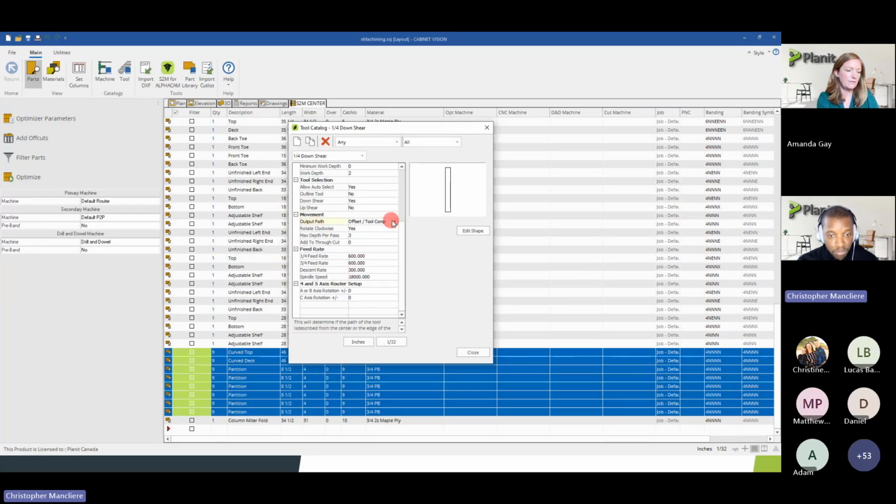It's always pretty much set already, so you want to use tool compensation. If you want to rotate clockwise or counterclockwise, that's something you can control here. But if it's for the material, there's a note here. If you want to climb cut, it will be at the material level. You have to go on the sheet and set in the material properties if you want to use a climb cut.